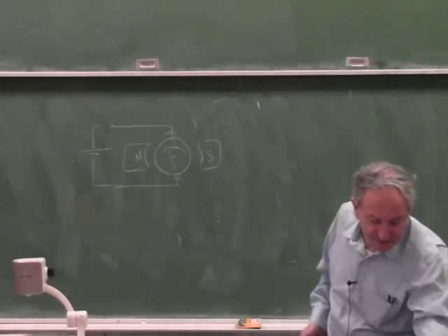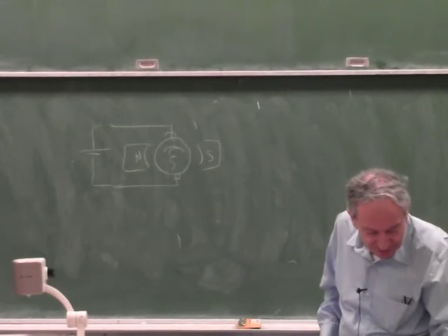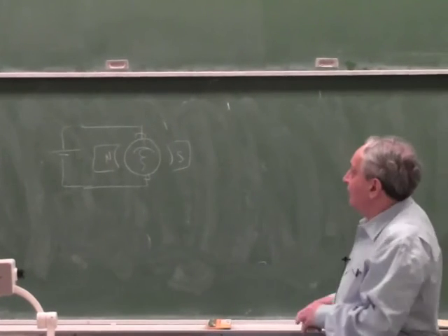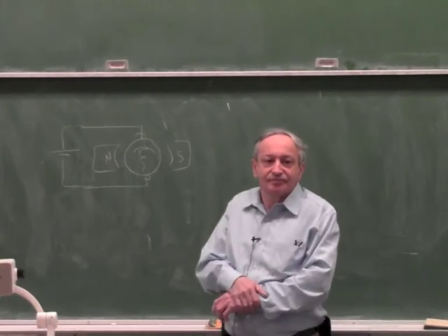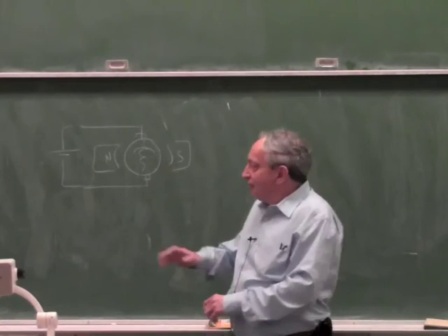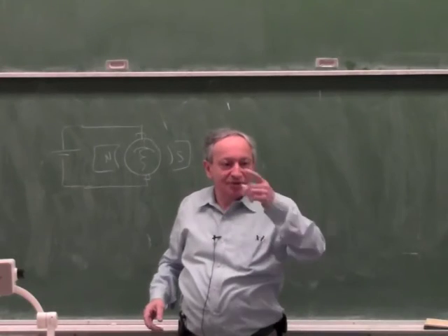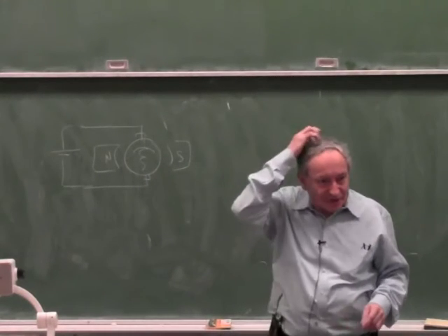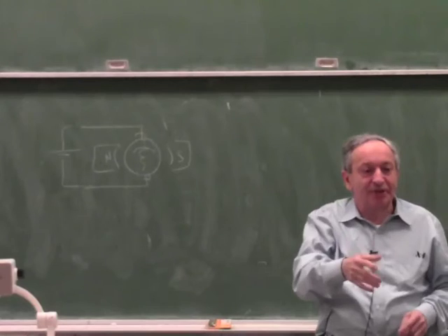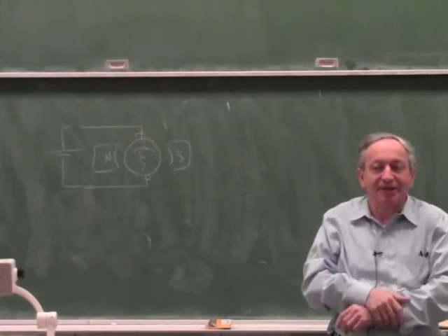Okay, so how do you brake a PMDC motor? Turn it off. Okay, if you turn it off, it's going to coast to a stop because it has inertia. Think of your hand drill at home or power saw. When you let it go, it slows down, but it doesn't brake sharply.